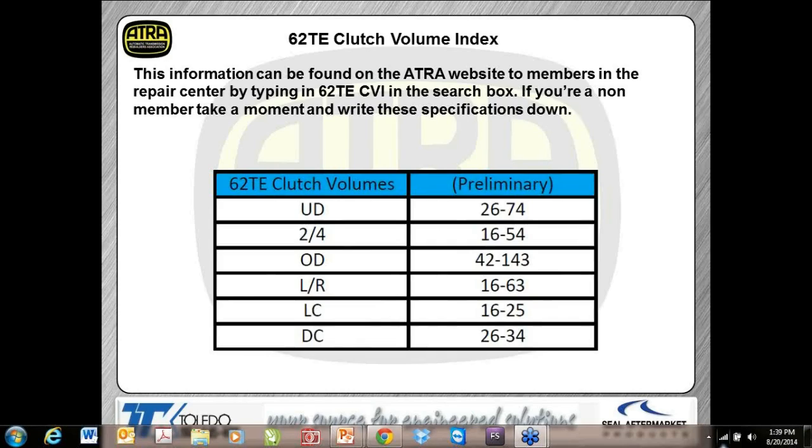Let's talk a little bit about the Sprague. One of the important things that I want to mention is you notice this blind spot here, this missing spline, and you can see the lube hole there. We want to make sure that we align that up with this slot. That's important, we want to make sure that the lube oil is getting down into the Sprague assembly itself.